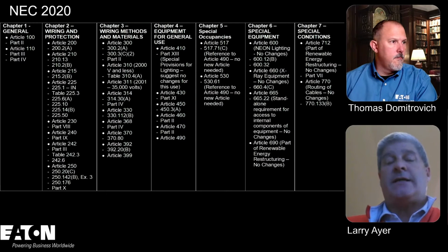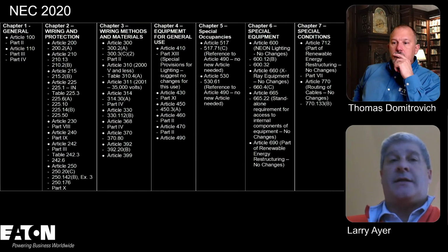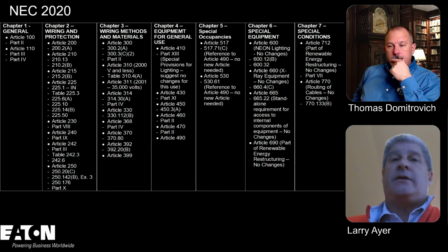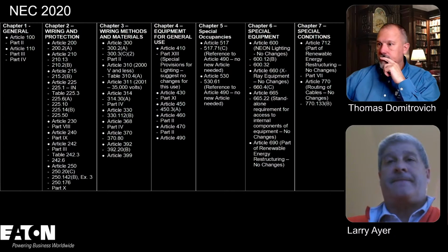If you try to find that same information for a medium voltage application, it's silent. There is no information to find. And so I think some people tend to get lost and go over to the NESC. Well, the NESC doesn't really deal with customer-owned equipment or installations. So there's a disconnect in some of these areas, and that's what we're trying to fix.